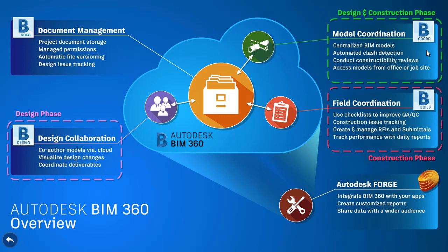There's another module here for BIM 360 Coordination. What that allows us to do is aggregate models together, because a project may not just be the civil components. It may be civil and architectural, and it could be utilities and other model components together to bring together a complete version of the project that works with a number of different disciplines. The Coordinate tools would allow us to aggregate that model and then start to run some analysis against that, looking for whether things can be built the way that it was designed, if there are clashes or anything that needs to be resolved.